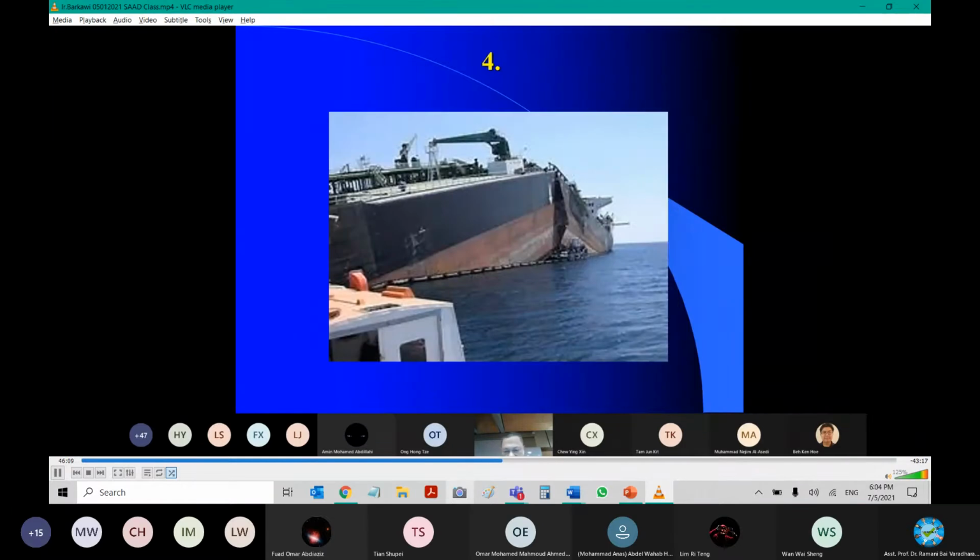A similar one happens there, right? This is a barge being loaded, still in the wharf. Basically, the crane is loading and unloading, and you can see it actually break into two in the middle. Again, looking at the buoyancies, I think there's some analysis and some papers being done, investigation, and it does actually have a high bending moment in the region where it cracked, right? So it is stress related.